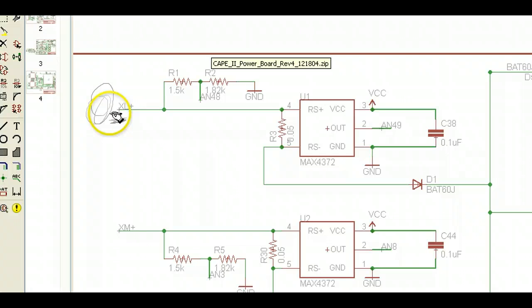But anyway, the solar panel produces power that comes in on this lead. The first thing it does, it comes to a resistor divider network. We call this a scaling network, and all this does is scale the voltage down, roughly to 2/3. Whatever the voltage is here, 2/3 of the voltage will be down here.